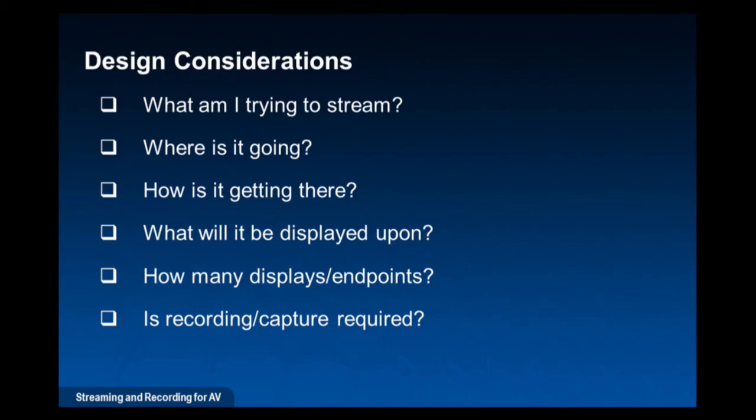So now you've got to buy another product that does that recording. So keep that cost in mind also. And now you've got to take that IP stream. How is it going to go into that recorder? Is it going to feed the recorder, or does this camera have to be split and go to 2 different locations? So those are the things that you need to take into account about, is it going to be recorded also?